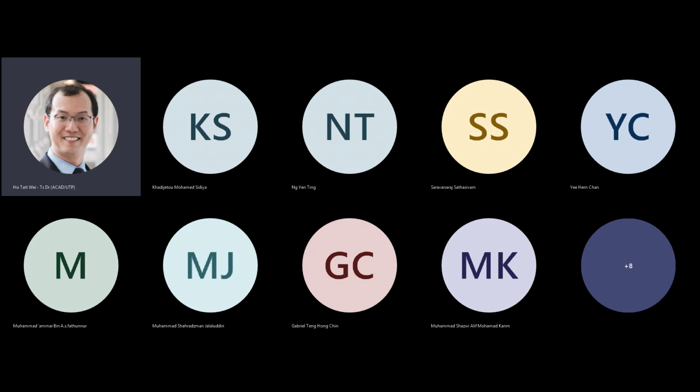And aging, also similar approach: if you created a device, a complex integrated circuit, when you use it over time, there will be a gradual slowing down of the speed of different parts of the circuit because of phenomena known as aging. There are 3 distinct phenomena that have been identified. We'll discuss them. And that can be analyzed from the perspective of changing or lengthening the critical path of a circuit.